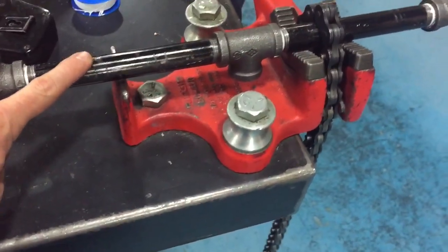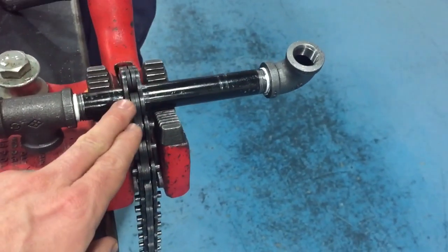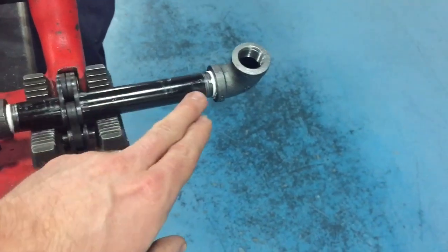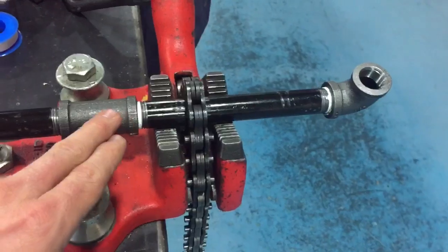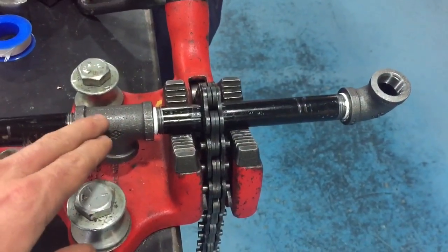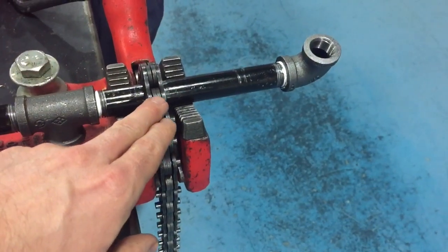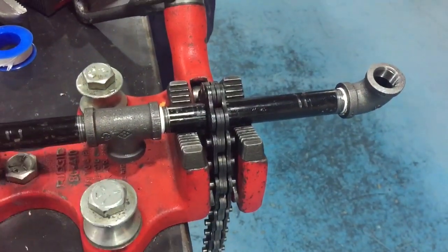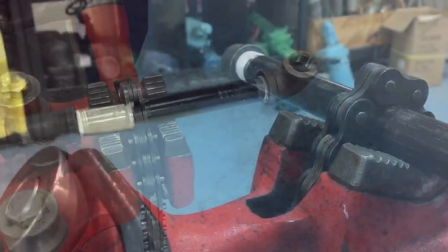I did have the chain vise strapped over here, but since I've added the T, I've moved it. So you want to make sure you have this chain vise strapped on and holding the pipe where you're going to be doing your threading, because if you start to tighten this, it might start to spin your T over here and things won't all line up. So make sure you're strapping this appropriately, putting it in a spot so other things don't move here. These other threaded fittings don't move, so we can get this one orientated the way we want. Alright, so I'm just about finished here.